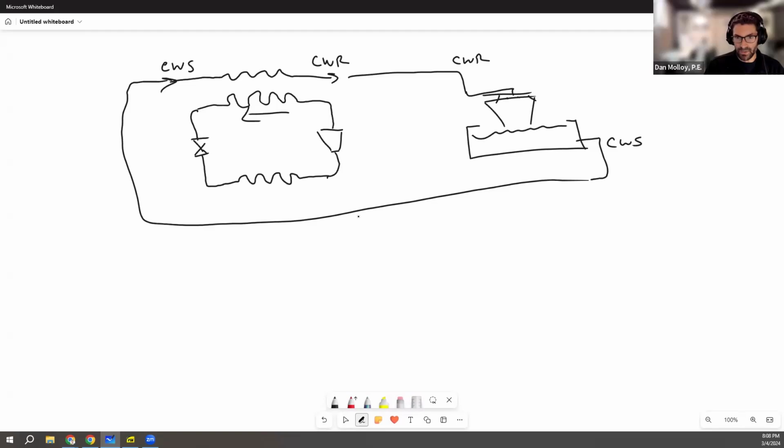And then the chilled water, which I didn't draw, is over here on the evaporator, coming off the evaporator. It's also a water-cooled heat exchanger. So these are both shell and tube heat exchangers where you have refrigerant in one and water in the other. And we're just using the refrigerant cycle as a medium to pass heat through as it goes into the chilled water and then into the refrigerant and then out to the condenser water. So there's a similar loop here for the chilled water. This guy would be going that way. So we'll go this way, coming down. So now this would be chilled water supply going here and chilled water return coming back.